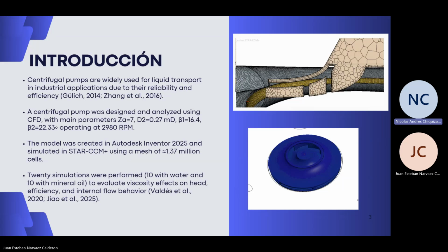The geometry was first created in Autodesk Inventor and later simulated in Star-CCM+, using a mesh of approximately 1.37 million cells. Finally, 20 simulations were performed, 10 with water and 10 with mineral oil, in order to evaluate how fluid viscosity affects head, efficiency and internal flow behavior.